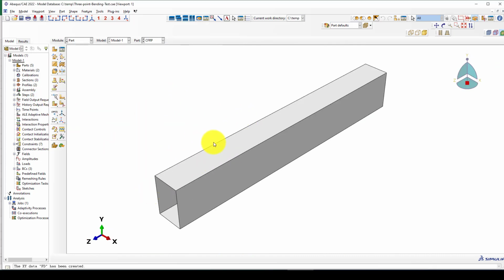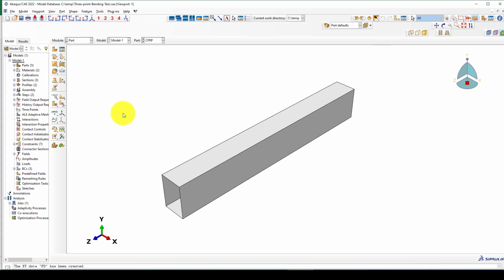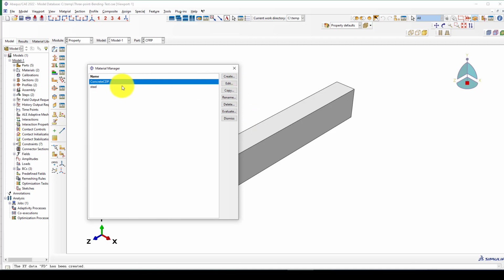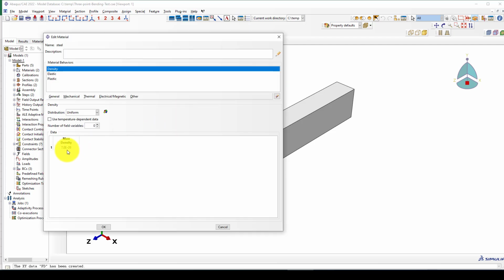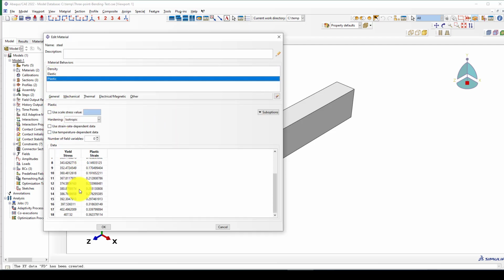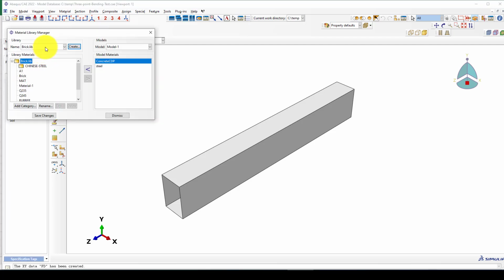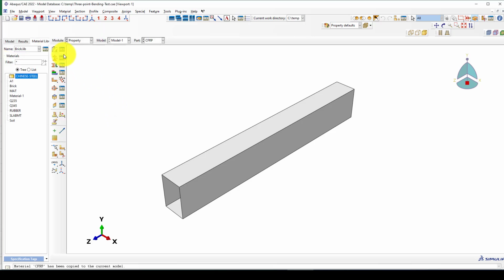Now we have created the CFRP as another box. We go to properties. In the properties, we should create a material for the fiber elements. For concrete, we have CDP, which has 25 megapascal, and steel rebar, which has an ultimate strength of 410. Now in my library I have some material. I can see here is a CFRP. I want to add it.